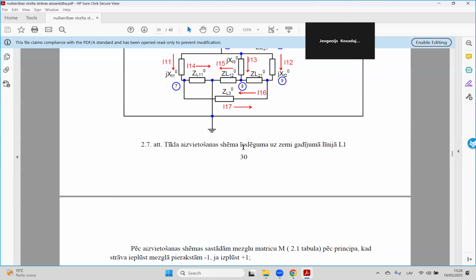You need first to make an equivalent scheme. You need to put all your input data into MATLAB. You need to get the correct calculation for every current, every node and every voltage, and then to draw a voltage diagram for the protection device. Yes, this is more complicated.